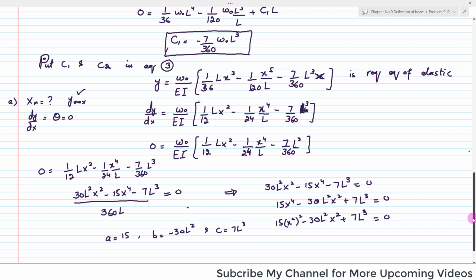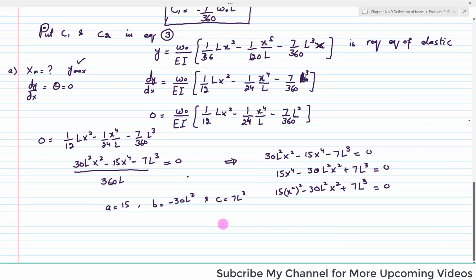I will just write the short version because it will be lengthy otherwise. So xm whole square will be equal to 0.269 L square. Further, if you take the root, xm will be equal to 0.5193 L. So this is the location along the length of the beam where the deflection will be maximum.